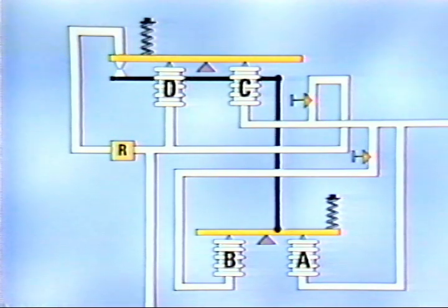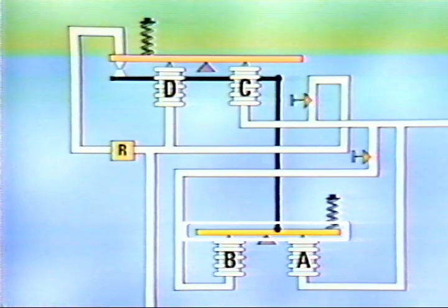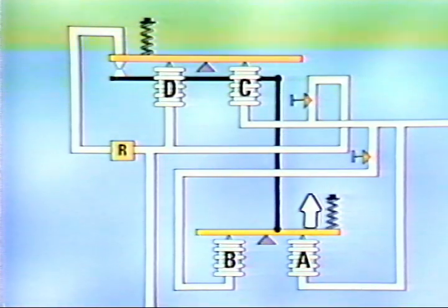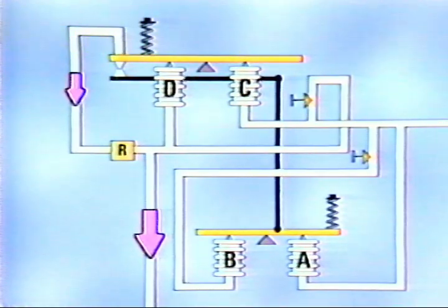If input were to increase, this beam would overcome the tension of the set point spring and tip in this direction. And this beam would pivot in this direction. As a result, both the flapper and nozzle move towards each other, providing an immediate boost in output. This is the controller's rate action.